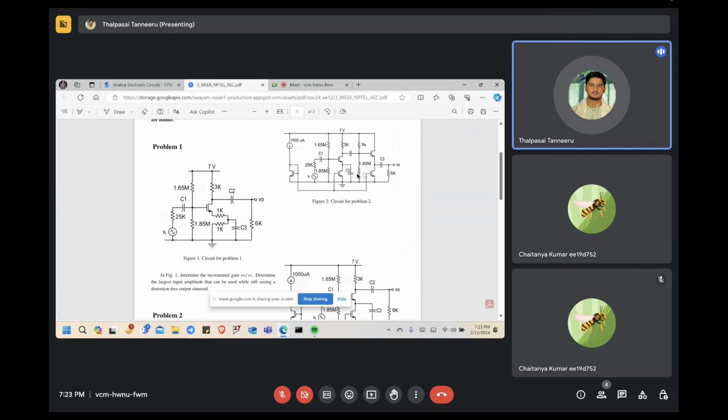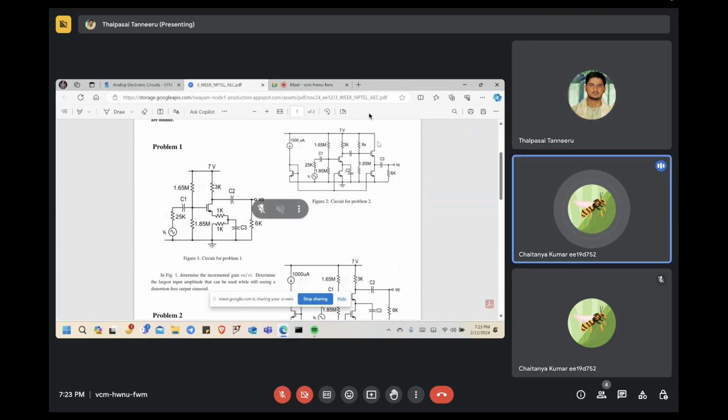Okay, lower transistor, this one also. So the same current will flow here. No, no. What I'm saying is, you find the current in all the branches, calculate the transconductances of the relevant transistors, and then you just apply the small signal analysis. In small signal analysis, you will have a common source followed by common drain. Now you said the output transistor is a common drain transistor, which is the common source?